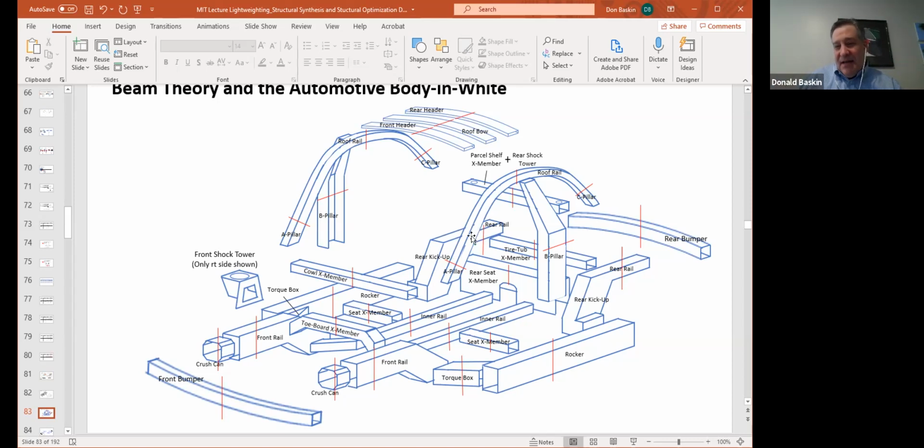The bottom line is that having a vehicle that doesn't deform in this roof crush mode is very critical. And so it's very important that these roof rail structures are made of high strength material. Volvo, I think, was one of the first companies, if not the first company, to make these out of boron martensitic steels. Strong stuff. I think they still do, and I think everybody sort of adopted that.